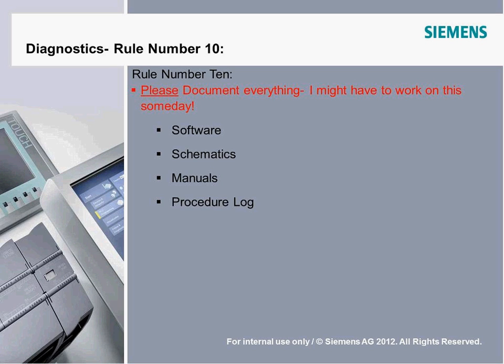Reproduce the problem. If you can reproduce the problem, you can probably fix the problem. Use your tools. Certainly with intermittence, we need to be able to look into and see what that check engine light means. Remember, it's not always the most complicated part, even though a lot of people will say that it's that crazy controller again. Treat the cause, not the symptom. I should probably move that up very close to the top. Document everything.